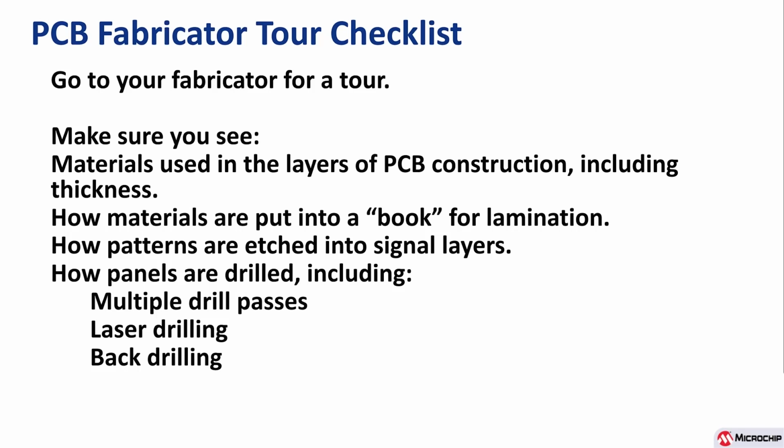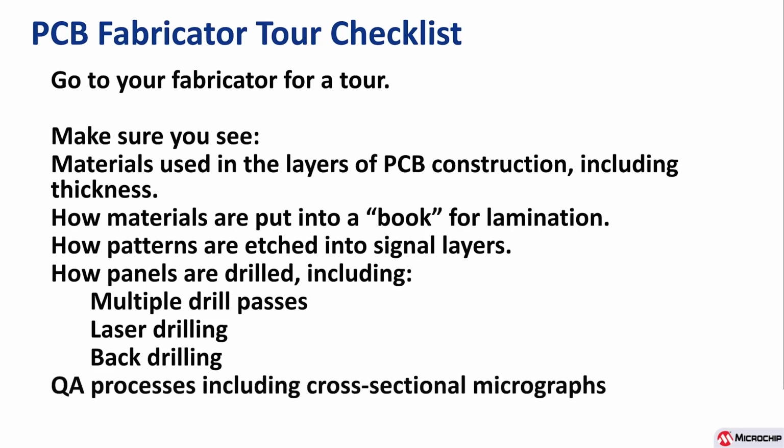So you're going to see how those patterns are etched. You're going to see how panels are drilled, including multiple drill passes, laser drilling, back drilling. Ask the questions, and then take a quick look at their QA processes, including the QC processes. And you can take a look at how they do cross-sections and examine those with micrographs and other details. This stuff will give you a really good idea of reality when you're talking to your fabricator on the phone about your stack-ups and other details, trace widths, spaces, gaps, etc.